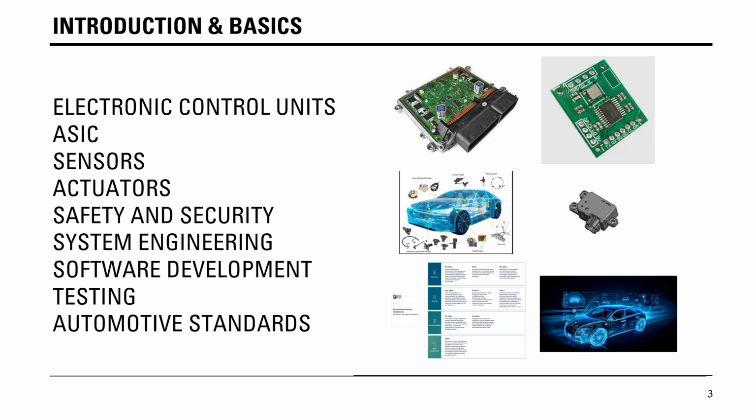So the main basics of automotive embedded systems contain electronic control units, where each control unit has its own specific job to deliver a function or a feature to the end user, like seat belt functioning, comfort driving, or safety or security of the systems. And of course, there might be several kinds of ECUs in each vehicle. Around 30 to 40 electronic control units might be present in the older architectures, communicating together using CAN or Ethernet communication protocols and delivering the functions to the end user for comfortable and safe driving on real roads.